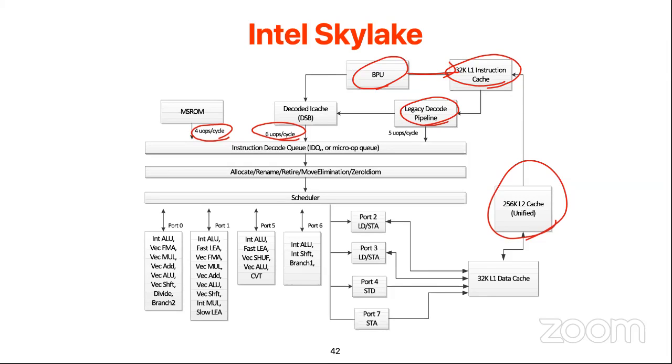You still have the L2 cache, L1 cache, and then after you decode an instruction, you have a unified instruction queue instead of separate queues like the Pentium 4. And then we have the renaming logic, and the retirement logic, which is actually the commit logic. So it's essentially implementing the reorder buffer, and the scheduler is the issue stage, as we mentioned.